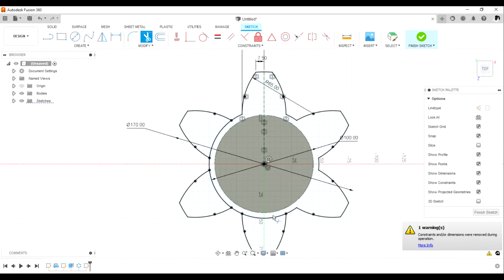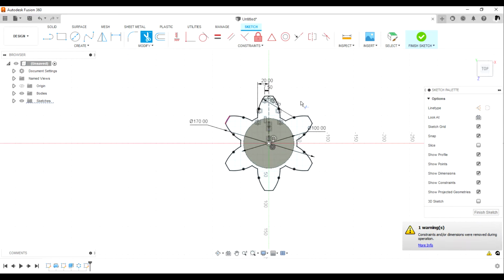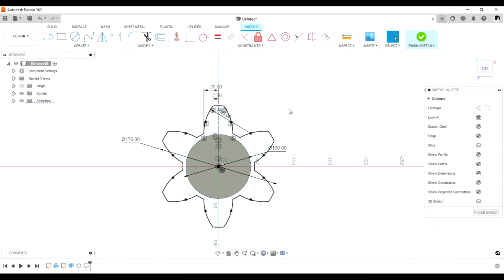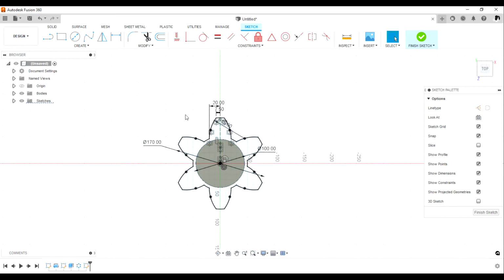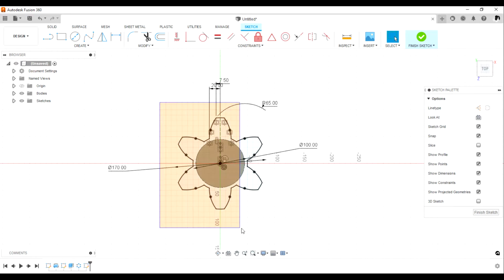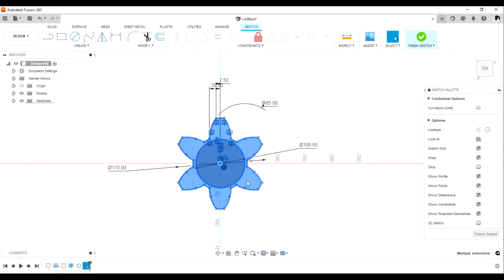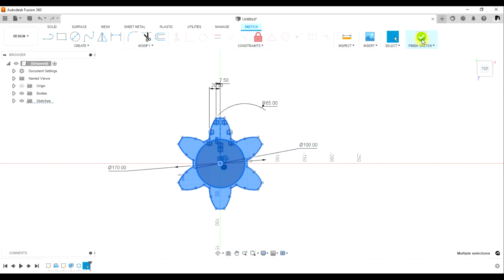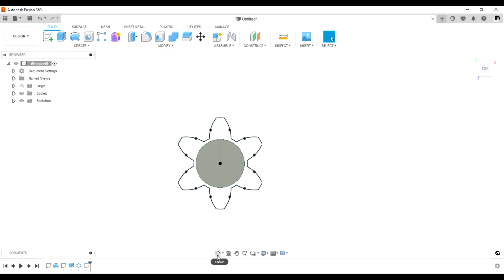So technically, this is going to be the first sketch. We need to make a total of 3 sketches. So this now at 100%. Then the second sketch is going to be at 75%. Just while on the sketch window, you select everything. Select like that, then copy, Control C. Copying like that can only happen while you are still on the sketch window. Once you Control C, then complete the sketch.